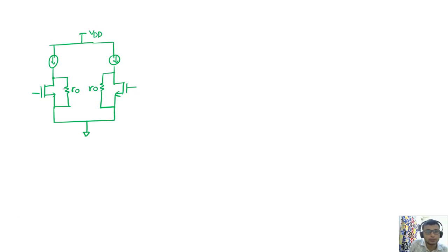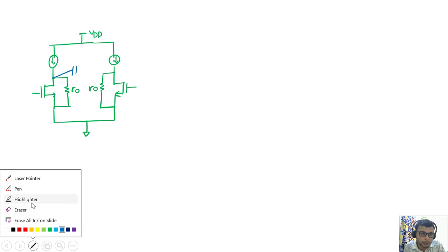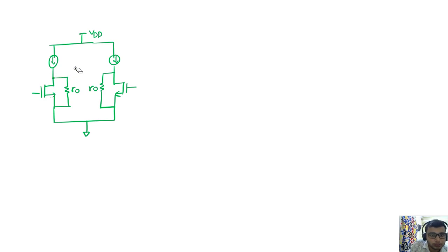So overall we can see one thing here. Whatever resistor or capacitor was present here can be split into two parts and shorted to the virtual node, the virtual ground node. Okay, so it can be shorted to the virtual ground node. So any resistor which was present in between can be split into two halves, and they can represent nothing but the R out of the transistors.